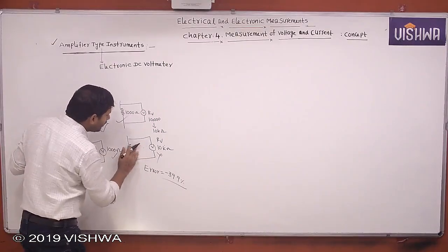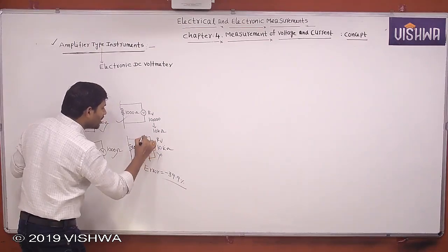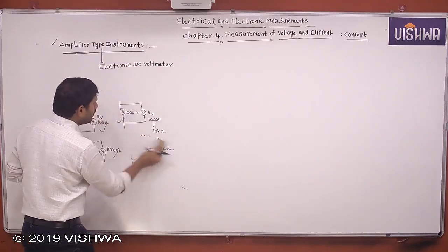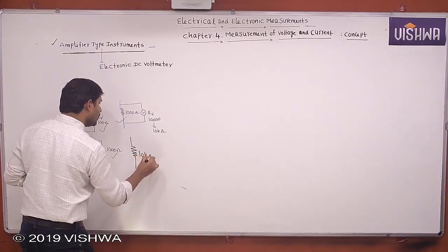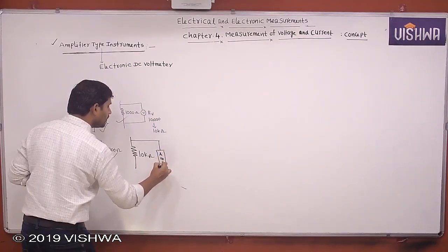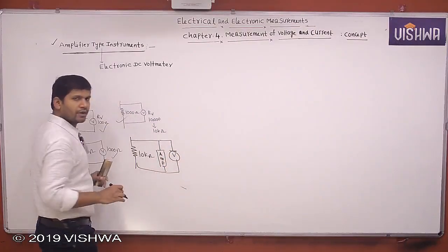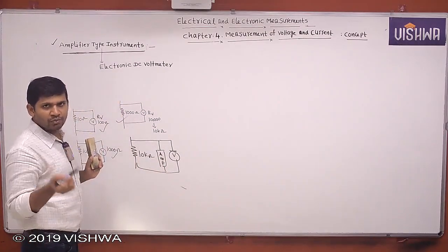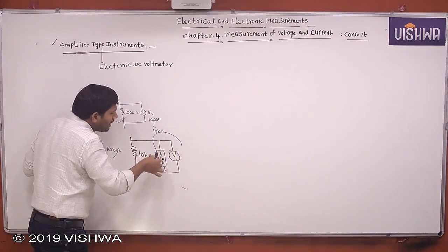So directly we are not designing it. That's why, in front of the PMMC, we are placing one amplifier. Now we design it like this to measure the voltage across high resistive loads: in front of the PMMC, we use one amplifier. Internally it consists of the PMMC voltmeter. Now we know that amplifiers offer high input resistance, in the range of mega ohms also. Clear? Once the amplifier offers high input resistance, this total combination will offer high input resistance.